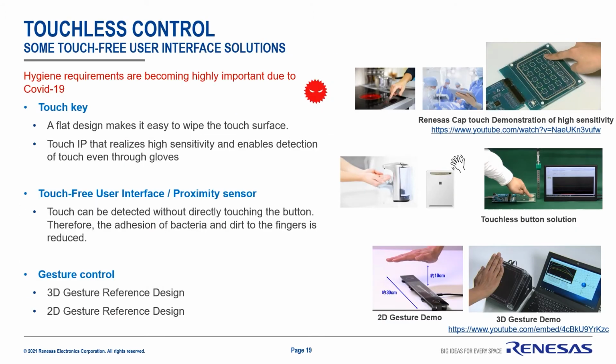Our technology is able to support touch and touchless interfaces. Concerning touchless, we can consider two types. Proximity: a function similar to the traditional touch, but at a distance. We want only to detect a finger's presence. Gesture control, where we would like to recognize the movement, the gesture of the hand, in order to control the appliance.